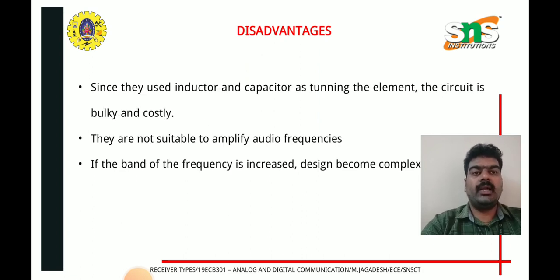And then the drawback of TRF is that they use inductor and capacitor as the tuning element. The circuit is bulky and costly, and it is not suitable to amplify audio frequencies. And next, if the band of frequencies increases, the design becomes complex. These are all the disadvantages.